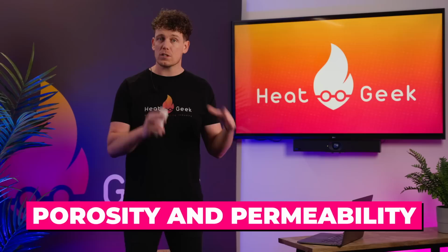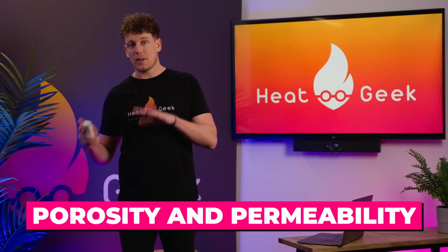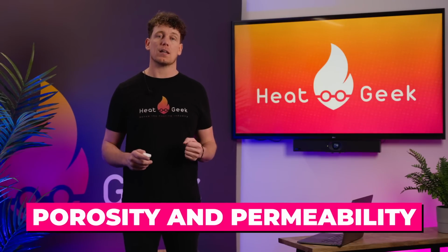The ground should be conductive, which requires moisture. Dry ground will conduct less heat. Holding water is not enough though. The water must move and replenish. As such, both the porosity and the permeability will need to be approximately understood.